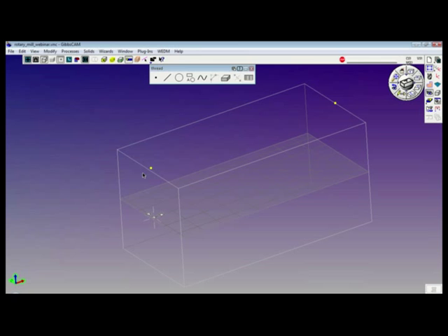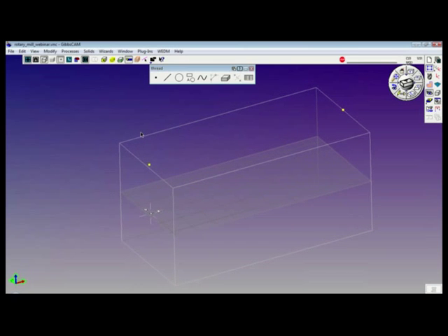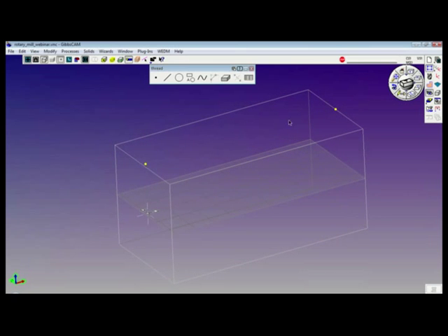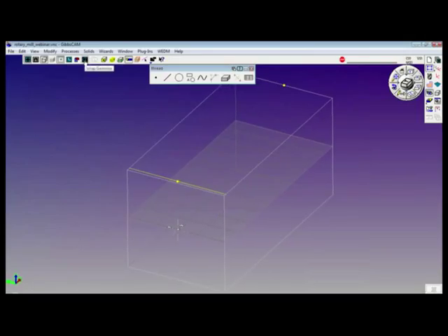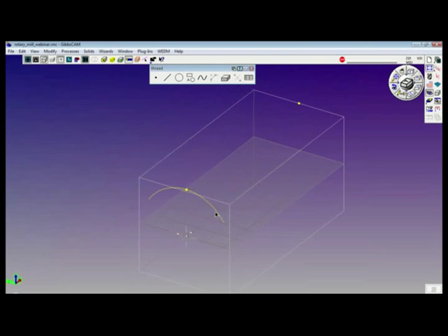So the next step is to connect a line from one point to the other. We do this in Wrapped Geometry. We select the line creation tile. You pick the two yellow points. Single feature creation. Look at the line. If I unwrap it, it goes straight. If I wrap it, it wraps around the radius.